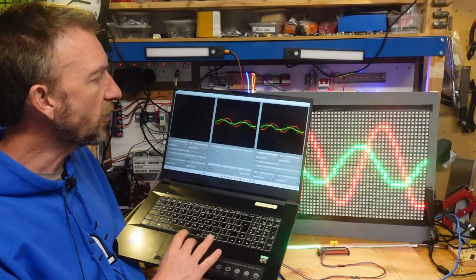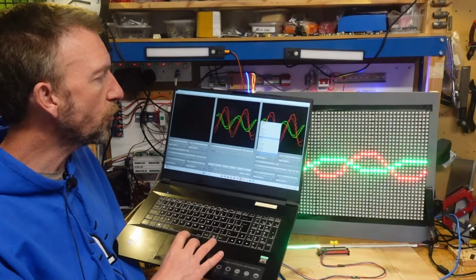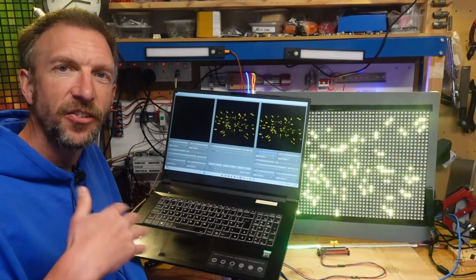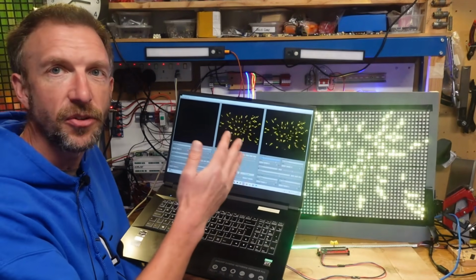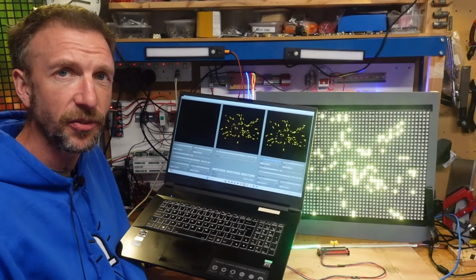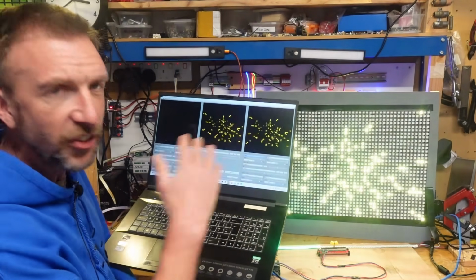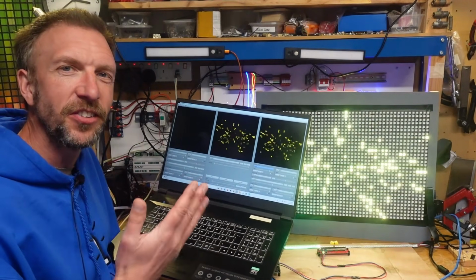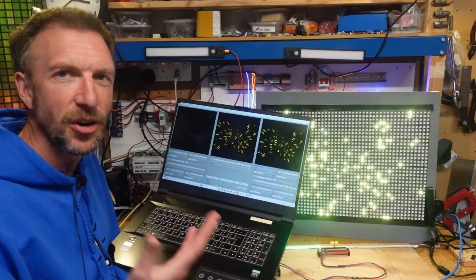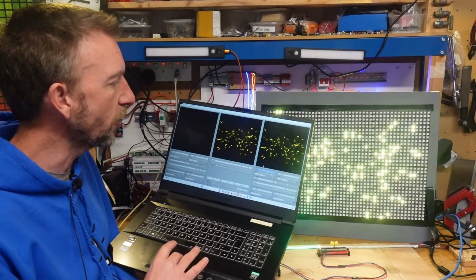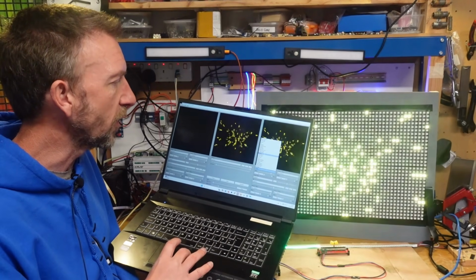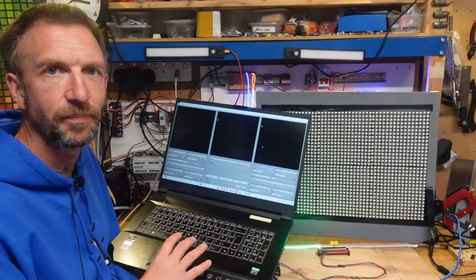The ESP32 only needs to retrieve that data and then send the RGB values out to the LED strip or any other lighting fixture. So instead of acting as a lighting brain, the ESP32 just becomes a dumb networked lighting node, which is much closer to the way that stage lighting fixtures would work in a theatre.